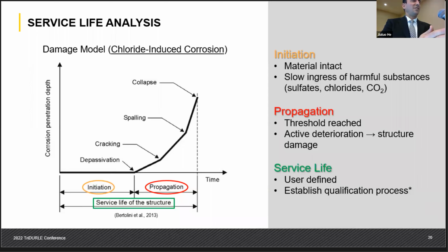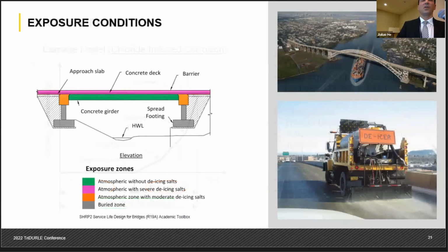A definition for initiation is more conservative and doesn't allow propagation, right? A definition of initiation and propagation is also technically correct, but then you have a different way of managing that level of damage, right? So you need to incorporate maintenance. Then, understanding the different components of the structure and exposure conditions.